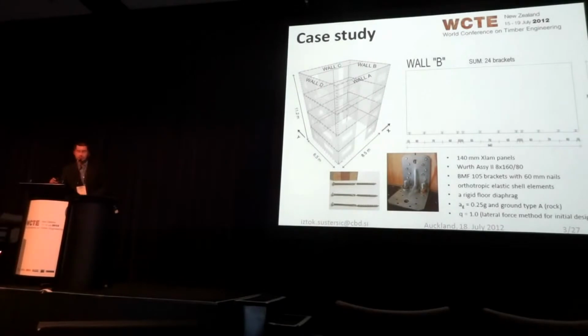This shall all be demonstrated on a case study building. This is not an actual building. We've thought of it in the last 2 years, and we're doing some analysis on it. I won't be talking about it too much because it's all written in the paper. Just maybe a few short things. So we were using the same type of connectors across the whole building, BMF 105s, basically because those were the only connectors that we've had some proper experimental response for, so hysteresis response.